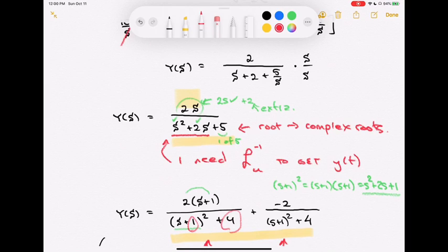I could have just done my standard approach, breaking it up into 2 simple first order terms, which would have had complex modes, and it would have had complex coefficients. And when I inverse transform them, I would have had some additional simplification step to get what I know has to be the current here, an expression that looks real.